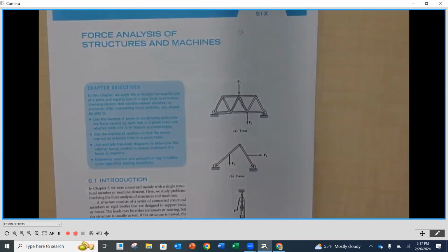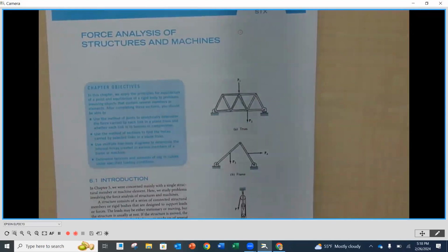Strength of materials, yes. And most specifically, what is the type of material that we're going to want to make this structure or this truss out of. Many times we see bridges made out of steel. Okay. And they're made out of steel because when I can have loads being in tension or compression, steel is one of the few materials that, for a couple different reasons, it's relatively inexpensive to make. It's actually quite inexpensive to make in comparison to others. But it also has this ability to reverse load almost identically in compression as it does in tension, which is really cool about it.